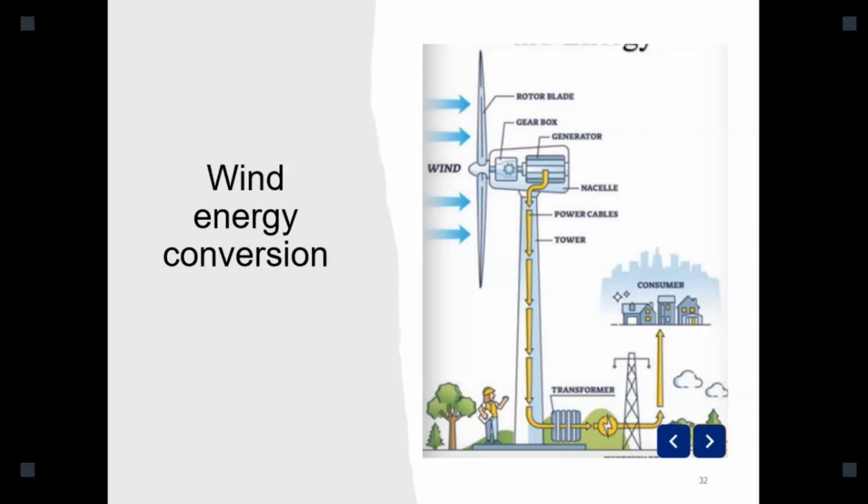The reason is that the rotor torque-speed characteristics need to comply with the generator torque-speed characteristics. Normally, generators may require higher rotational speed. Actually, the rotational speed of generators depends on the number of poles inside. That is an electrical concept. If we have a high number of poles, it can generate energy at a lower rotational speed. If we are not using a gearbox, we need to use multi-pole generators, meaning a high number of poles, directly coupled with the wind rotor. But commonly, because multi-pole generators may be expensive sometimes, a gearbox is also used. This is the concept here.